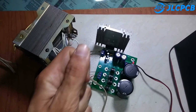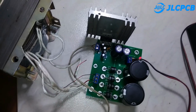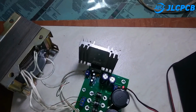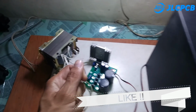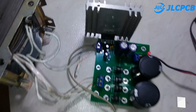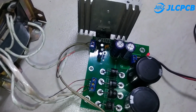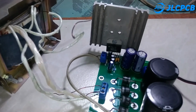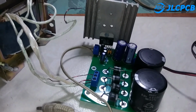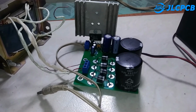But the main thing here, you will see that it's not working. Why is it not working? The LED is turning on, which means that the circuit is powered, but I have connected this speaker and you cannot observe any noise or any disturbance in the signal, means that the amplifier IC is not working. So why is it not working? The most important thing of the IC TDA7294 is the mute and standby functions, and in this design I did not include the mute and standby functions, so these functions are not included in the design. So what to do now?